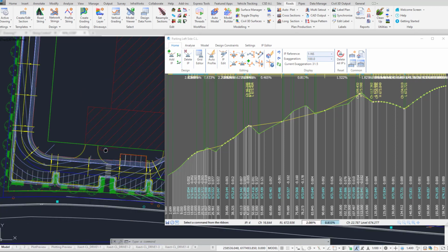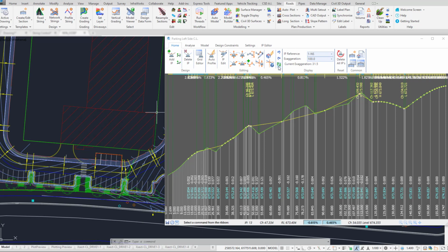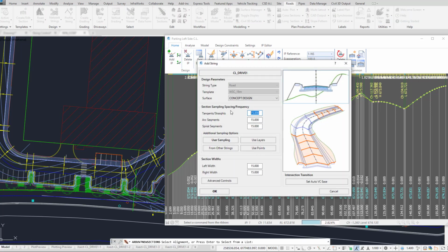One further step here is to show you how the refresh button works. So I've got some sample positions here that are being used for the reference point entry. I'm probably going to just go ahead and resample to create a lot more to give me a better rate. So let's just put this up to 2 or down to 2 for the tangents of the arcs.